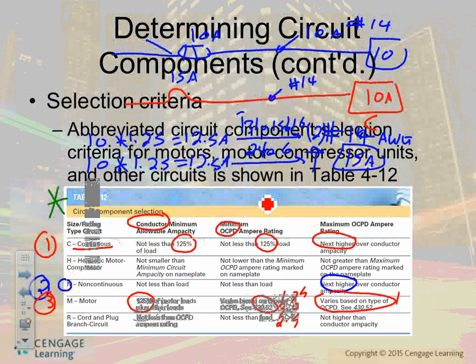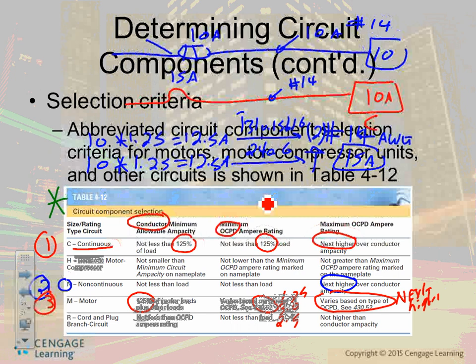Typically, if it's not a standard size, they allow you to go to the next higher one, almost always. So you end up with a 33.3 amp fuse. Do they make a 33.3 amp fuse? They allow you to go to the next standard, 35. In all of them, guys, you're allowed to go to the next standard.